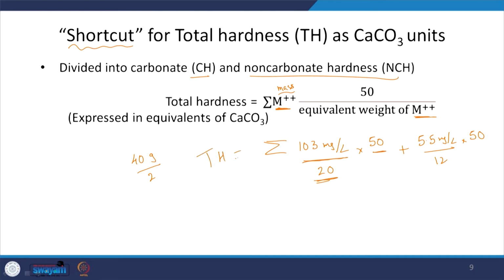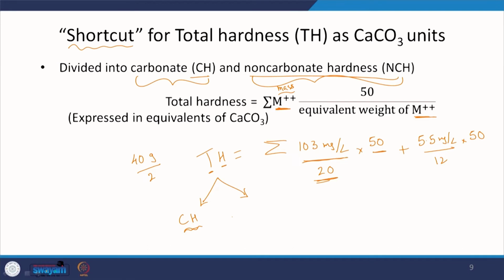And what is this new term total hardness, and why am I having to classify it further into carbonate hardness and non-carbonate hardness? So, it depends on how easily you can remove it. So, carbonate hardness is the hardness that can be removed if you are able to heat up the system, right. This is just for classification purposes, but we will see why it is relevant later, right. So, the hardness that can't be removed when you heat up the water, you are going to call non-carbonate hardness. Carbonate hardness is typically the one associated with magnesium, right, and calcium too, some of it,